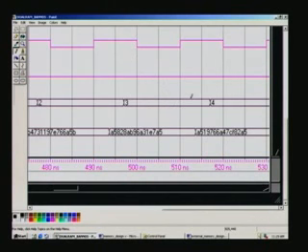How is this dual RAM different from my getting two separate RAM chips and making use of them? Even there, how will you access vertically? Suppose the organization is 8 into 64 bits. Suppose you have used a conventional memory of 8 into 64, right? That will be only one address bus. When you give an address, it will merely access row wise and give you the data. All memories are designed in that fashion while reading. Whereas our requirement is that while writing it should be horizontal, while reading it should be vertical. Right? You can imagine it as a matrix.